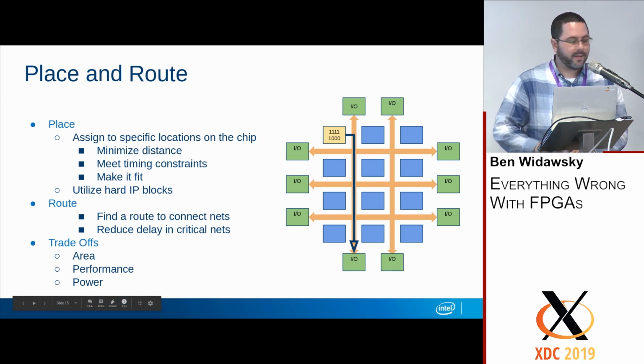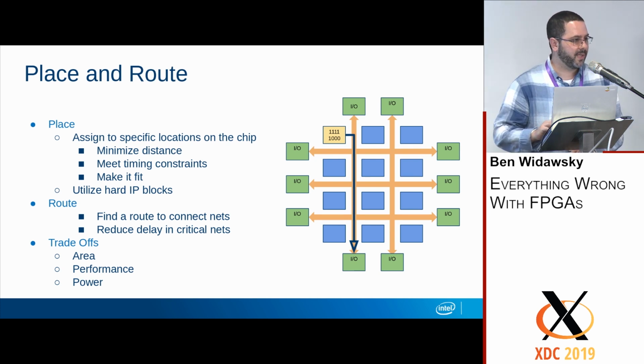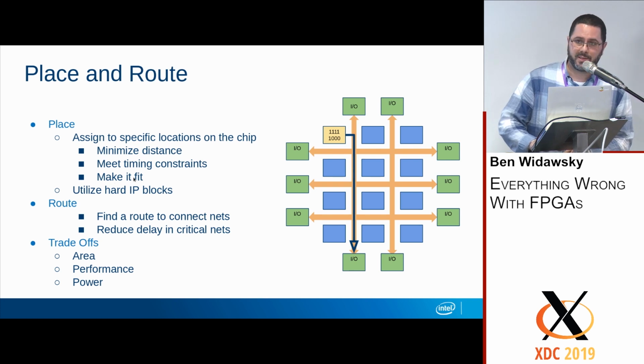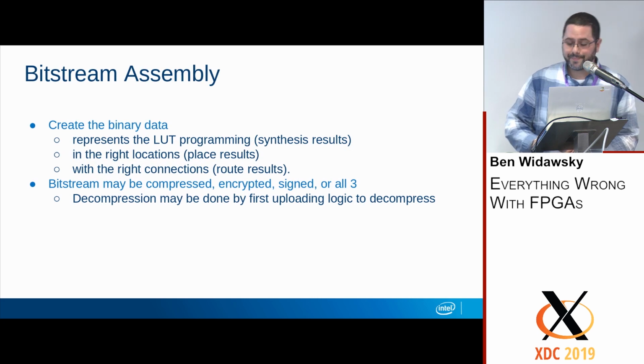And again, I'd like to point out that the information of the floor plan and how things are tied together is what's not published, and most of the fuzzing efforts that take place today are figuring this out. The synthesis part of things, what the LUTs are made of, the size of the LUT and what's in an ALM and so on, that's actually in public documentation, and that's to support the third-party EDA tools.